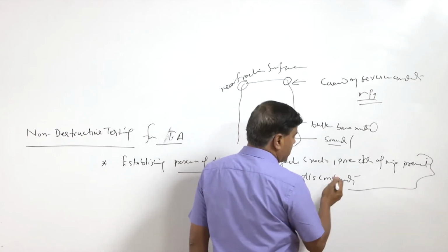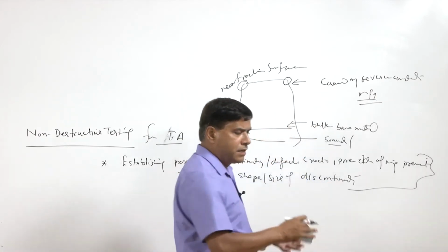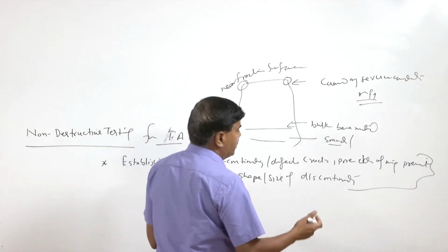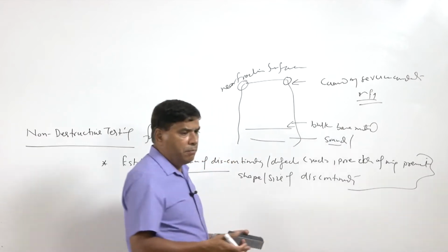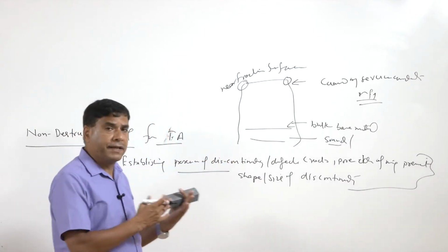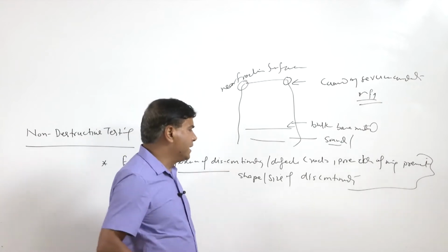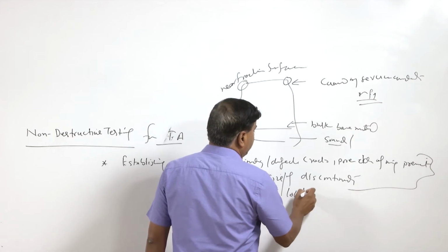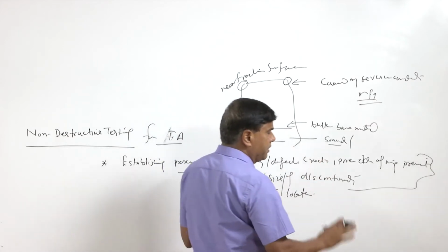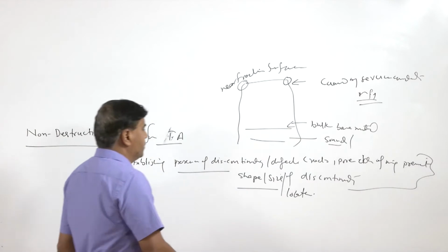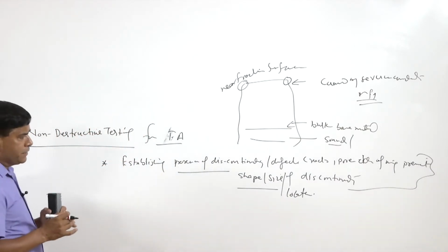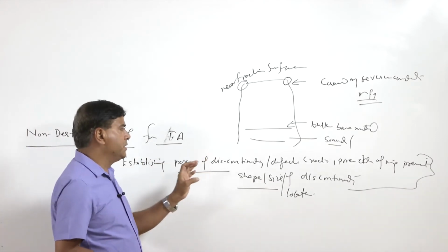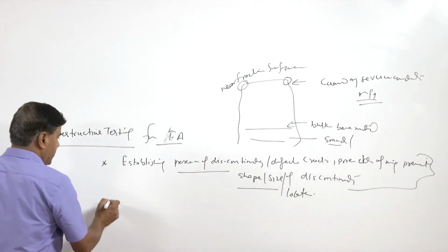If the discontinuities are of large size at a critical location, then of course they can be considered a major possible contributor towards the failure, but that will be established only through fracture mechanics analysis of the entire situation in light of the size, shape and location of these discontinuities in the component which has failed. So, it provides the basis for the failure analysis due to the presence of discontinuities, if they are established through NDT.